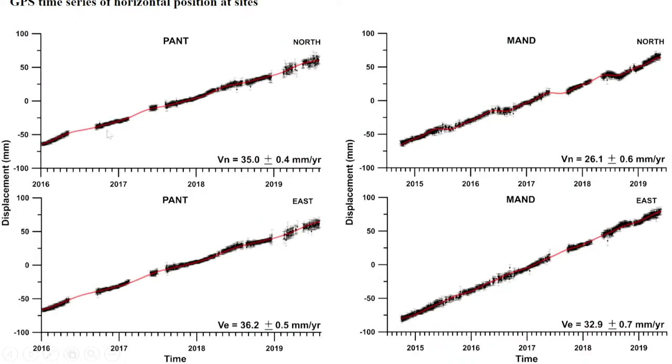And this is the continuously operating reference station sites. Continuous data displacement you can see. You can also see some gaps. This is mainly due to many reasons, maybe a power issue or the instrument not working well. That's why there is a gap in the data. Here also you can see the gap. If the displacement is going up, it means displacement is mainly occurring in the north direction. If the displacement is going down, displacement is occurring in the south direction. This is how we interpret it.